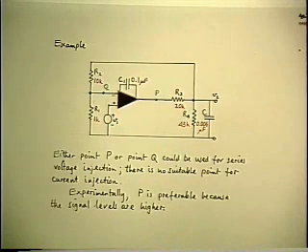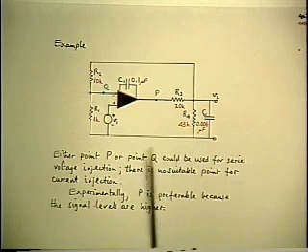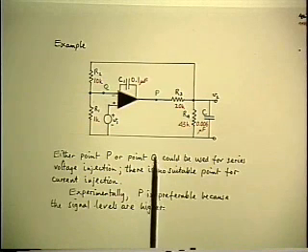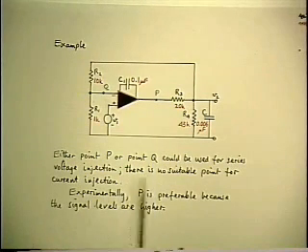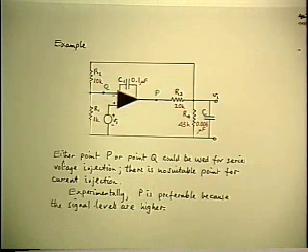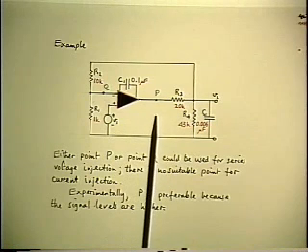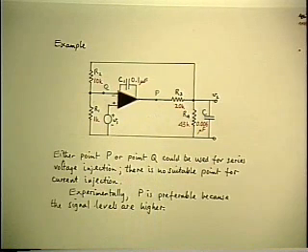We simply want to assume that we've analyzed the system and we're going to measure the loop gain and see whether we're right. So all we have to do at this point is do the analysis first to predict the loop gain, because as I've already mentioned, you always want to do that in advance. Otherwise, you may waste a lot of time taking measurements that turn out to be useless. So you always should have an idea what to expect before you start. So all we'll do with this is we'll do the analysis to find out what the predicted loop gain is.